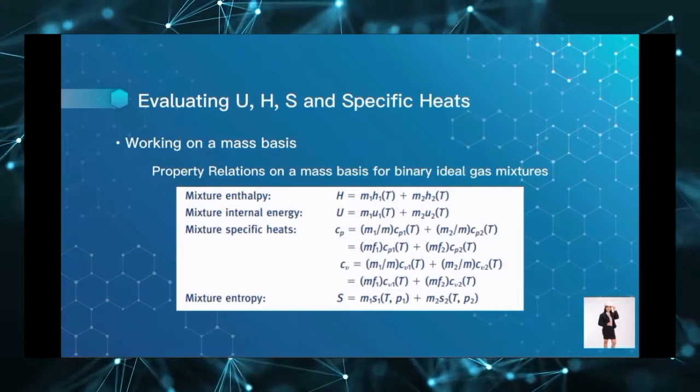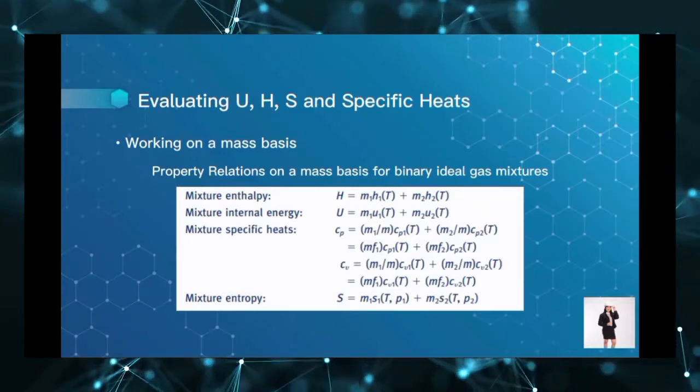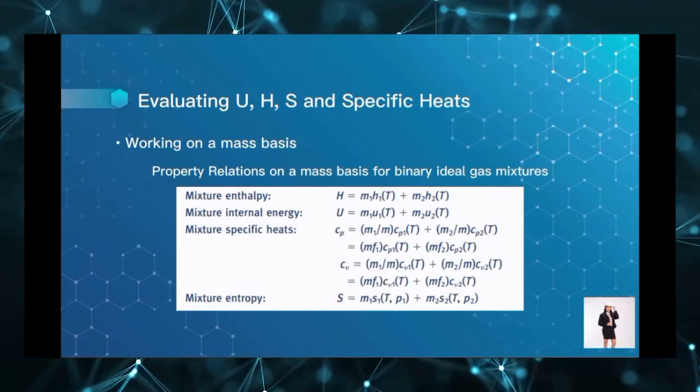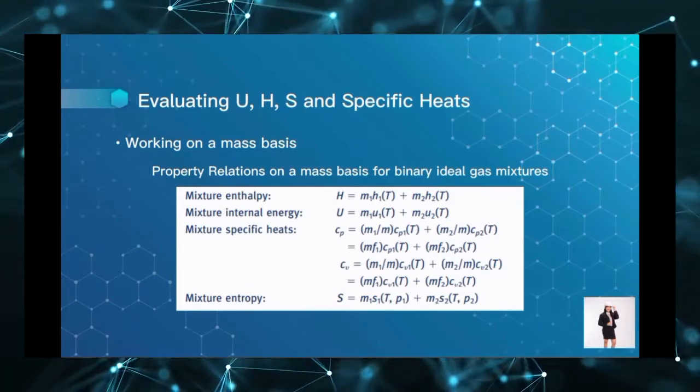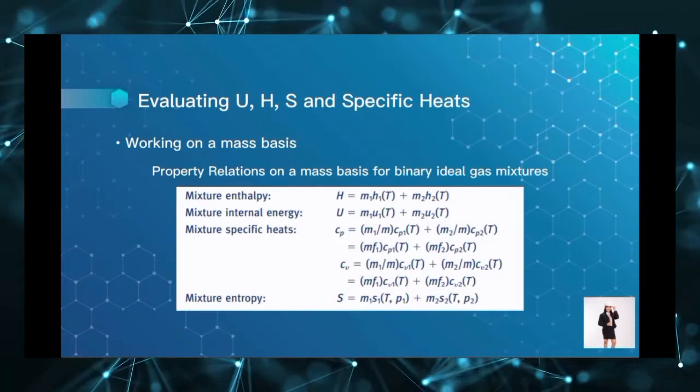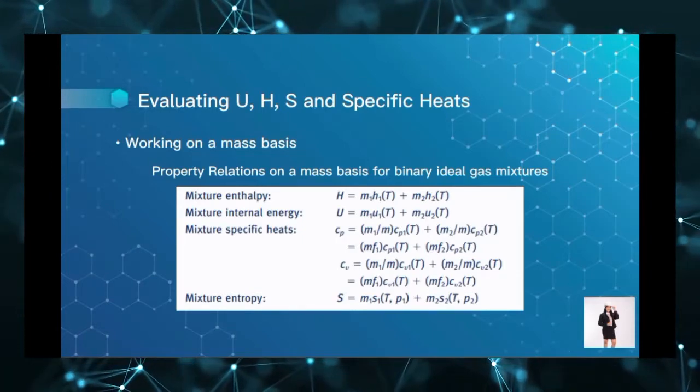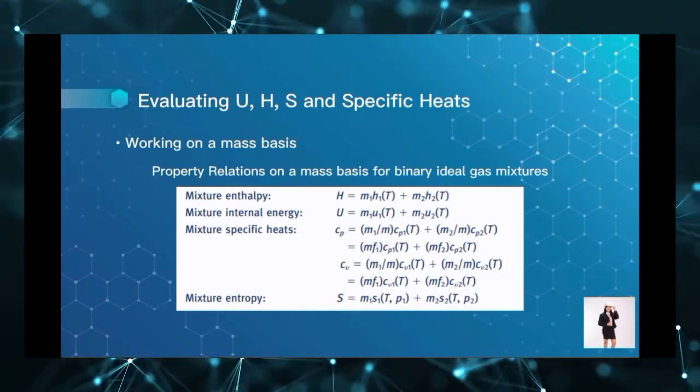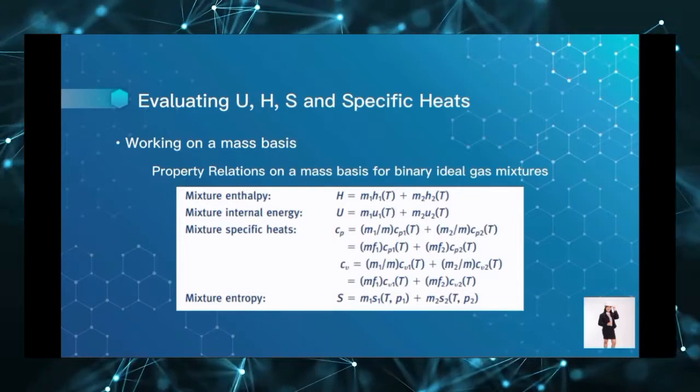The mixture enthalpy, internal energy, and specific heats are still functions of temperature, and the mixture entropy is still a function of temperature and partial pressure. So mole fraction in the molar basis is replaced by mass fraction of component i in the mixture entropy.